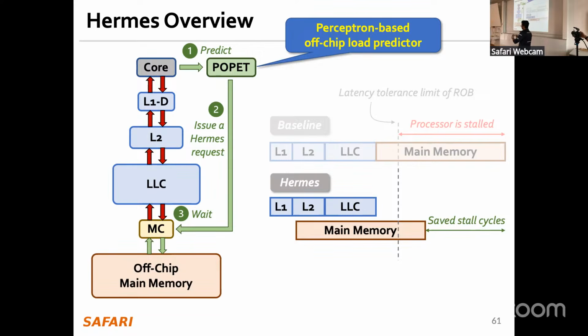So it is very similar in time, like 4. If this takes 5 cycles to access, the TLB would probably take 4 cycles to access, or maybe 5 cycles. That's why we say that L1 access latency and the TLB access latency are kind of the same. So the latency I'm showing here is not the L1 data cache access latency. It's actually the TLB latency that I'm not covering.